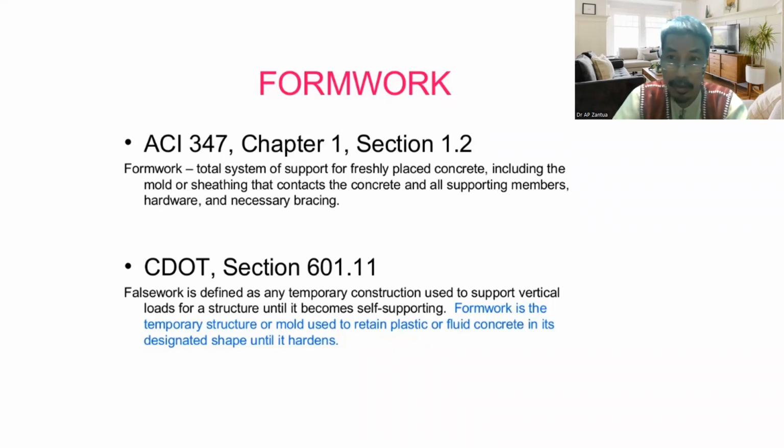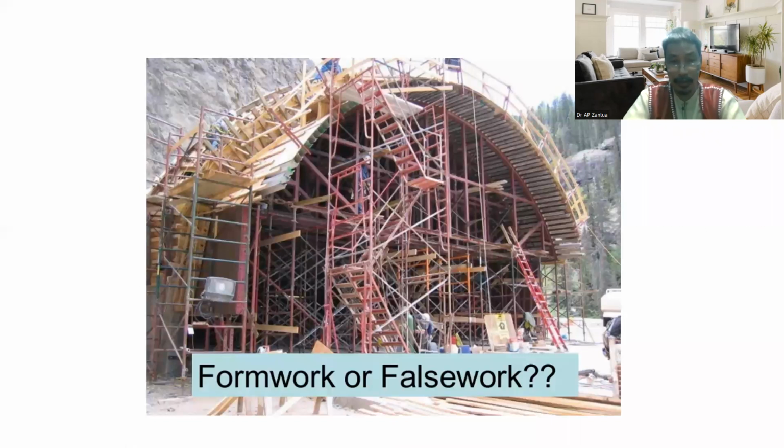So falsework can or cannot be in direct contact. Those structures that are supporting the formworks, we can also call falsework. They are not in direct contact with the wet concrete, but still they are temporarily supporting the structure. So everything you see here, all of these are falsework. But what are the formworks?